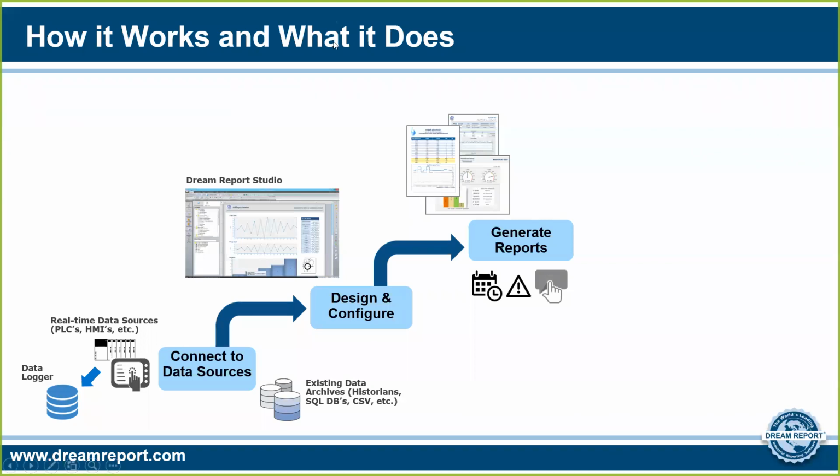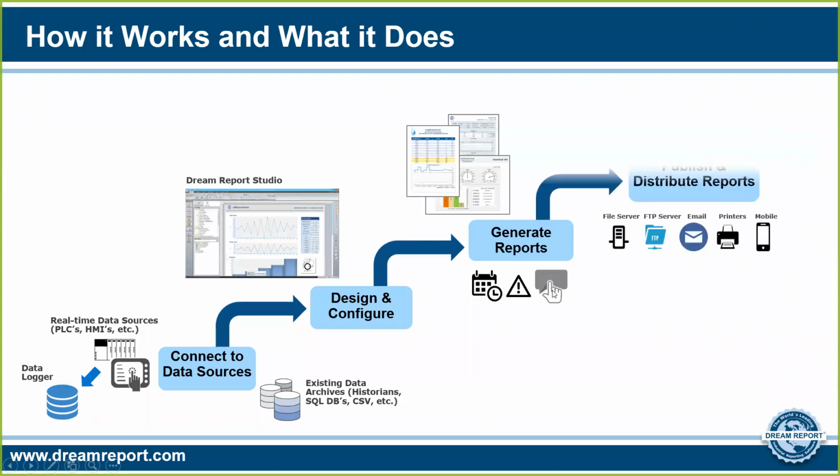The other interesting thing about event-driven reports is that you can take calculations on one report and trigger another. So for instance, maybe it's a shift or even a periodic every 10 minutes, an OEE type report is generated. If an OEE, say, drops below a certain value, use that calculation on one report to trigger maybe a more detailed downtime report as a consequence of that calculation on the first report. So that's automated reporting, then of course on-demand, and we have several interfaces for on-demand reporting as well.